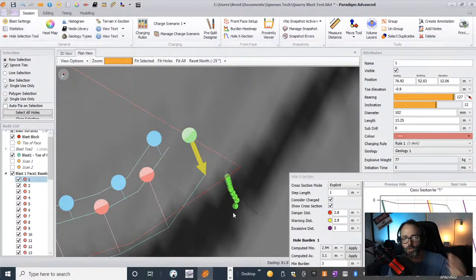So if you knew that this rock has jointing that runs that way and is naturally running back on that angle, and the blast hole is definitely going to vent out that way because you saw a crack in the face or something, then that's something you want to consider. Increase that burden, shift that blast hole. Don't intercept the jointing, don't intercept the hazard or the problem.